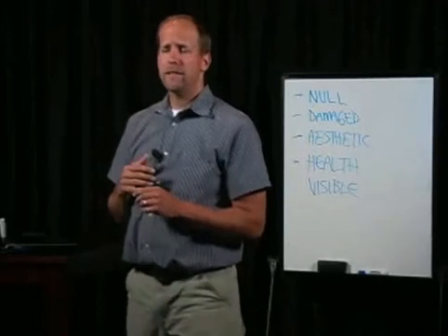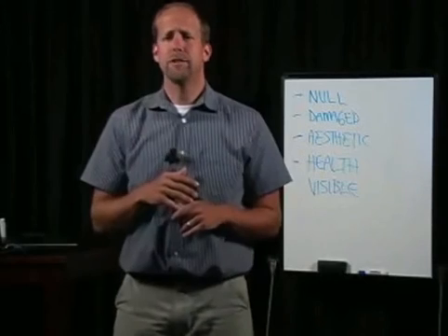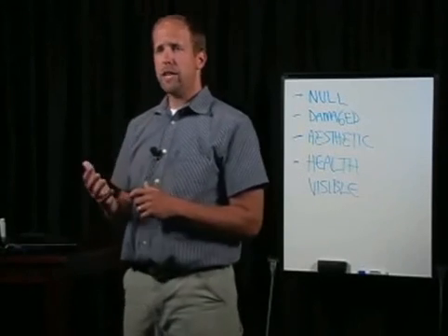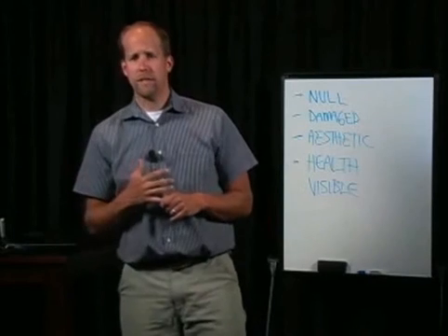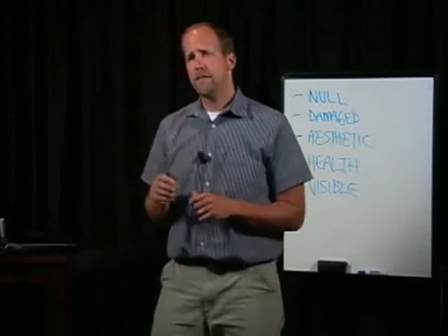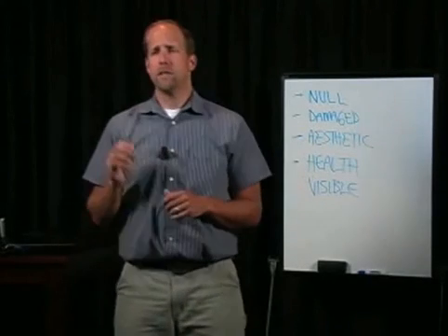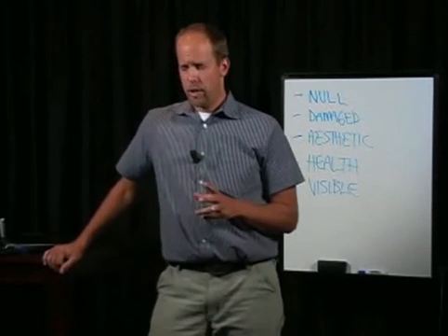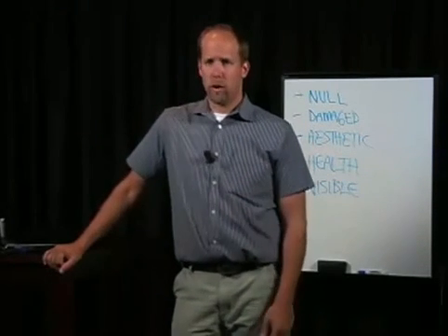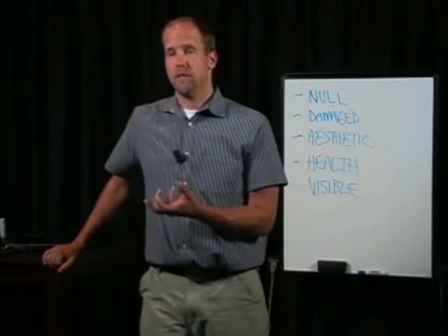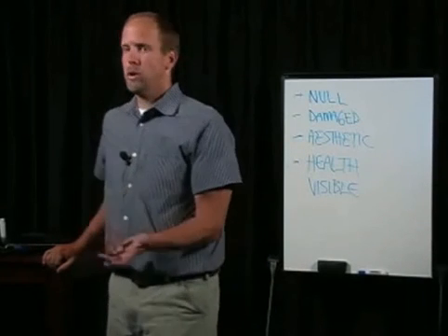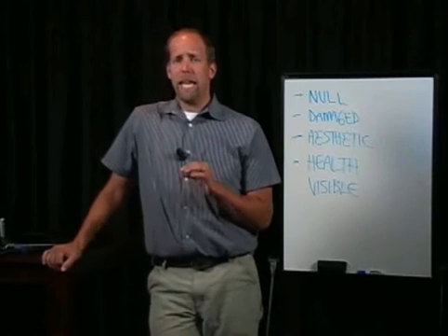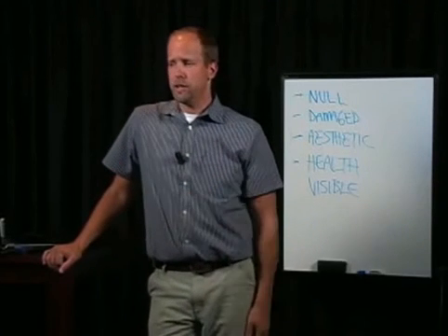Step 6, ask your client about their concerns with the building and the apparent condition or conditions of its systems and components. Ask your client if they are aware of or suspect any conditions that have led to moisture intrusion, water damage, conditions conducive to mold growth, or the actual existence of mold growth, or musty odors. Develop hypotheses that can be answered by a visual examination and sampling.